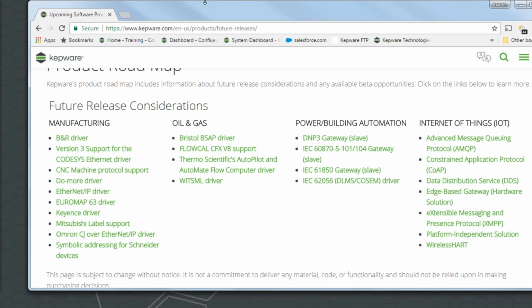The answer there is it is already automated. So license activation transfer in 6.0 is much more streamlined. It can be done all from the KEPServerEX license utility. No need to do that manually, Abdullah. And the Kepware installation can run in a silent mode. So if that's something you're looking for, running that installation automatically in a silent mode where you don't have to go through the wizard, contact our tech support teams and they can show you how that works. So again, in 6.0, all of that is set up and automated.